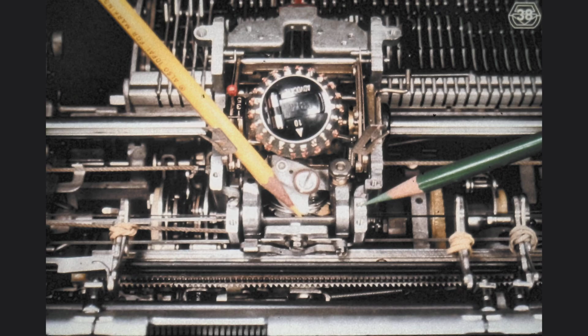The end play or side play of the rocker is limited or reduced to a minimum by loosening the set screw indicated by the green pencil and then moving the rocker shaft, indicated by the yellow pencil, from right to left. Since we are looking at the rear of the carrier in this picture, the shaft will have to move from left to right. In this manner, the retainer located on the left side in this picture will push against the right side of the rocker, thus limiting the lateral motion of the rocker. At that point, we should fasten the set screw and then check the adjustment for minimum end play of the rocker. The rocker can be regarded as the universal type bar of the Selectric typewriter.